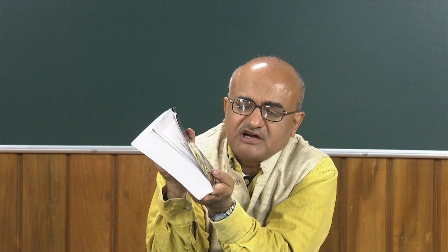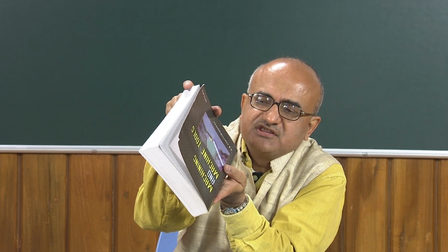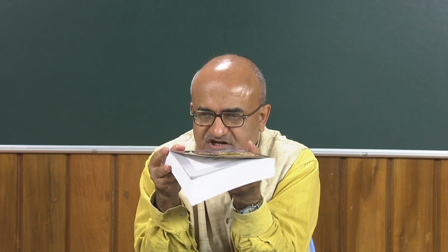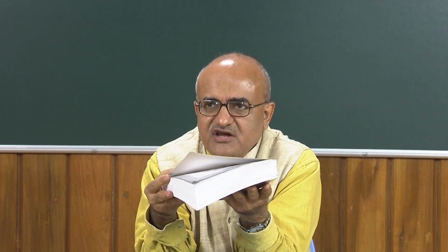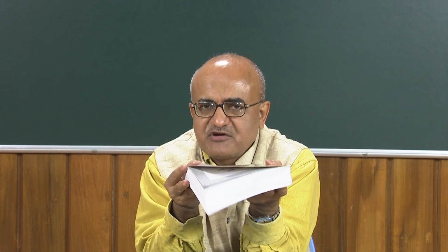So I have inclined it like this, but if I also incline it like this in the other direction, then that will be called the top rake angle. That means you have a surface that can be inclined this way and also this way. So then it gives a totally 3-dimensional type of picture.